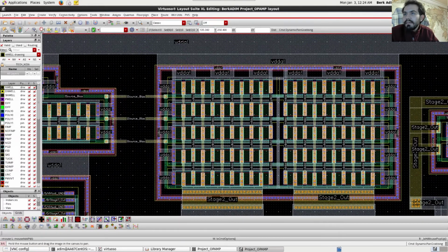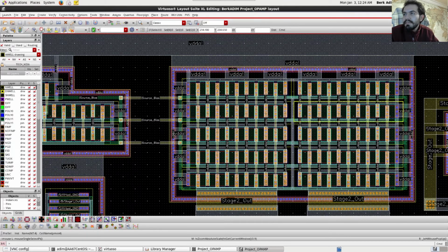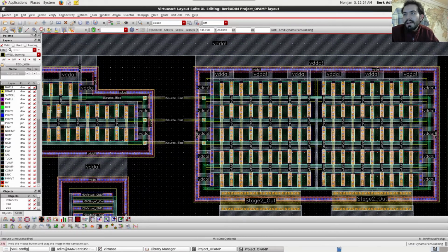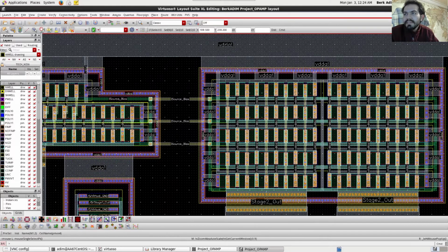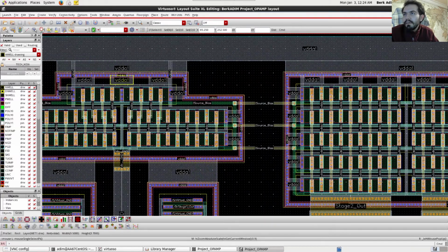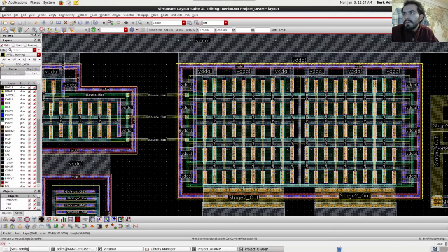And here, this transistor has twice the amount of width compared to this transistor. I am talking total width here. It has 6 of the same connections here compared to 5. So this is going to have half of the source resistance, which will mean it has the same source voltage. We can actually see that in our DC analysis. We extract the circuit from this design and run another analysis. I will just show you that in a moment.